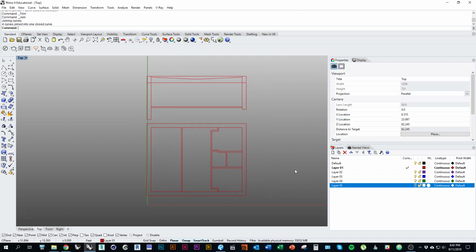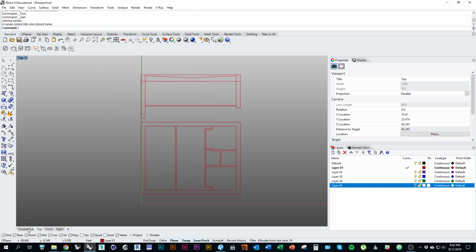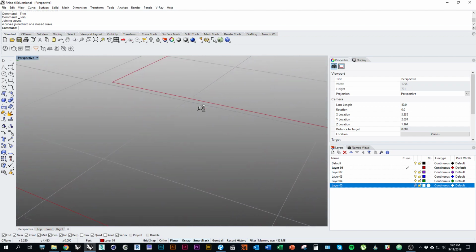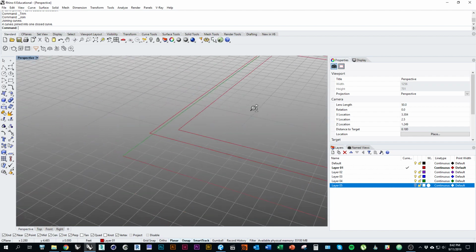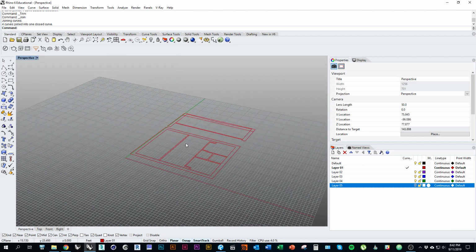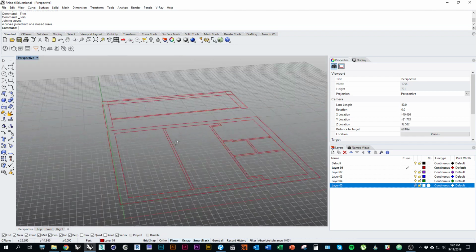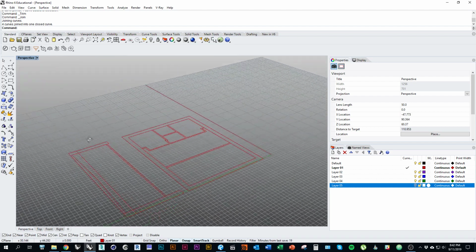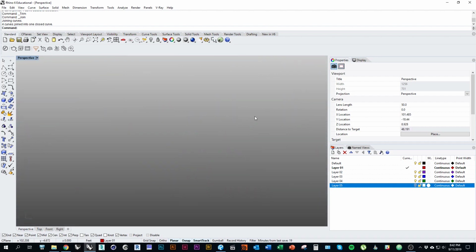All right. So now what I would do is I would move into 3D. So I like to work in 3D in a paraline view or one of your orthographic views. So in perspective, when you zoom in and out, sometimes you'll find that it starts to be difficult to see, zoom in closely, or things will start clipping, or your center of your orbit will get messed up.